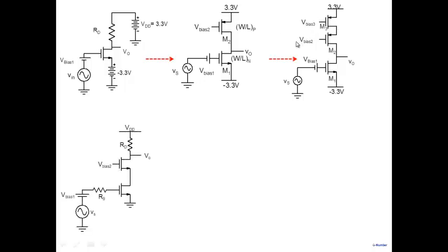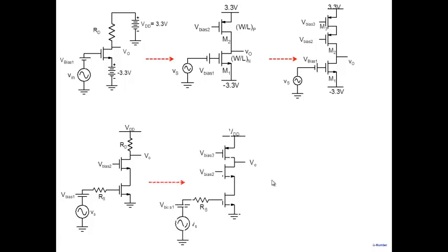The other one is, instead of building this amplifier, we could build a cascode amplifier. We just saw cascode amplifier, which will give you the same gain as this one, but will give you better frequency response. Now, again, this particular amplifier, if you want to build very high gain, you would require a large value of RD, right? And therefore, that becomes difficult. So what should you do to RD? Replace it by a PMOS. So you can get an amplifier stage which looks like this. What did we do? Same stage, cascode stage. Instead of RD, we put a PMOS load here, right? So you can see a clear analogy between going from here to here as compared to going from here to here. So you can build an amplifier like this.